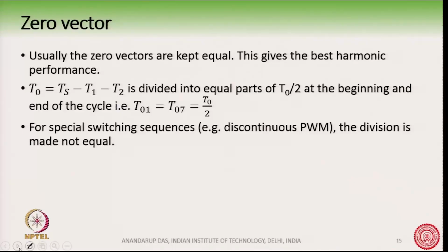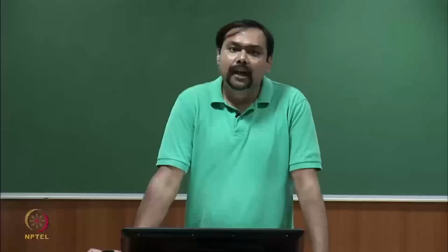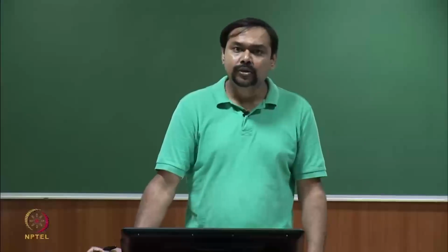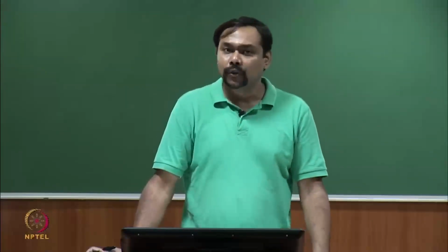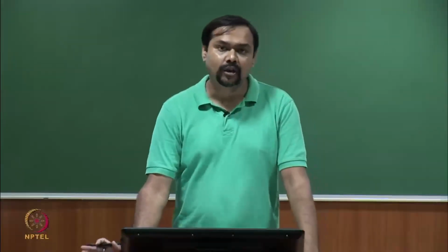Okay. And this is done in spite of the fact it will give poorer harmonic performance, but it is done for getting some other benefit. For example, like loss distribution or changing the losses in the switch, or say in neutral point clamp converter the capacitor voltage balancing and so on. So, these special switching sequences are used where the starting and the ending vectors are not of equal duration of time.